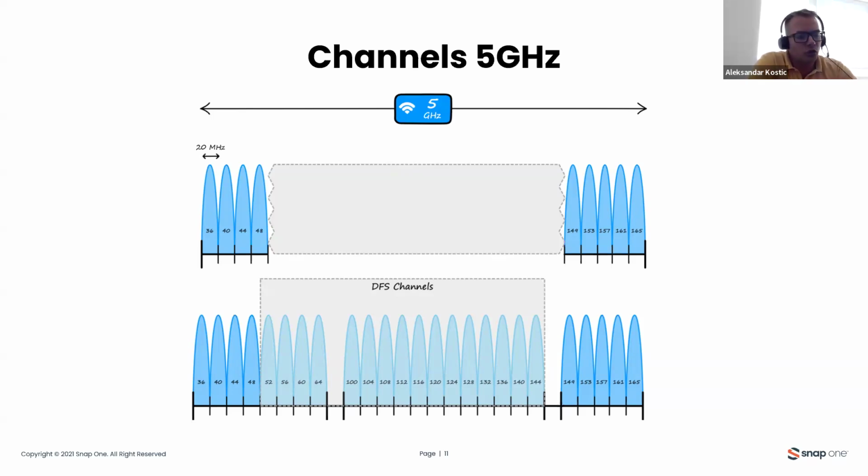When that is in question, in order to have a professional level of site survey, you definitely need some third-party application. Typically what we recommend is MetaGeek with its own Wi-Fi adapter, and it is able to completely show you the frequency map in a certain area and to detect what signals are there. But just to know, if we do a site survey at a certain moment and it is free, that doesn't mean it will always be free. It can happen that a signal jumps in and causes the signal to drop out.